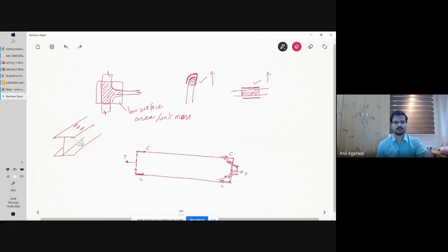Then what you do is, you cut strips from this in such a way that each strip gets one strain gauge. Okay, and let's say you had set the initial strain gauge strain value as 0. After you cut them, you will see that those strain gauges develop some strain. Okay, so now you cut that strip. Now you got this standalone strip that is cut from this beam, and now the strain gauge has got some strain in it. Earlier it was 0, now it has got some kind of strain. Okay, what does that mean? Now, of course, you are sure that there are no stresses acting because I've cut a very thin strip and I'm not applying any stress from outside.